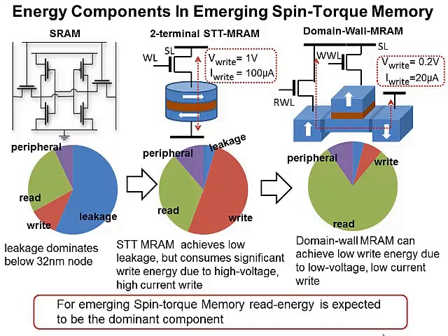So one of the most important advantages of STT-MRAM is that it is a non-volatile memory technology, and as a result the leakage energy is very small. And apart from that, density comes as another big advantage. Here each cell uses just one transistor as compared to 6 in an SRAM.